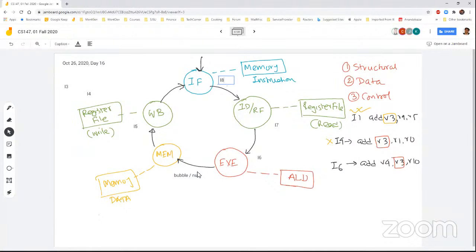So you see there is a delay induced here to make sure there is no data hazard, and that of course will affect your performance. Now in this case, instead of 5 cycles, it suddenly needs 6 cycles, one extra cycle to get it done. So that means it is decreasing the performance. And there will be many such dependence cases in a program. That is one of the reasons it cannot achieve the full potential of 5x speedup. Questions so far?